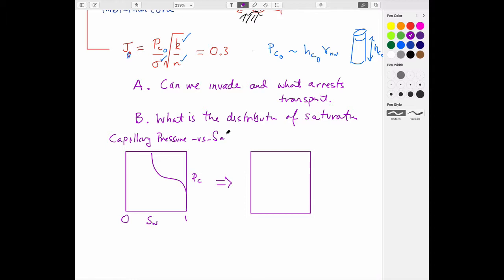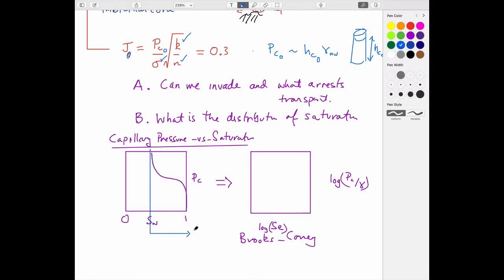Versus saturation curves. And we also talked about these Brooks-Corey curves, which was just another way of drawing them as log of capillary pressure divided by unit weight of the fluid, because it comes from agricultural, and an effective saturation, which we defined last time. And we noted that effective saturation just truncates this curve as effective saturation going from 0 here to 1 here instead of this scale.